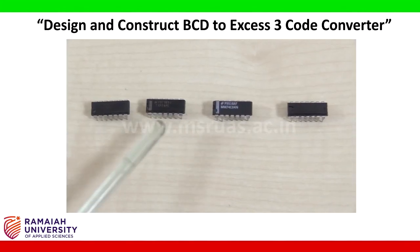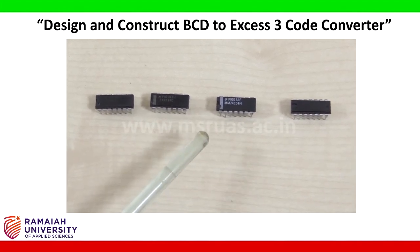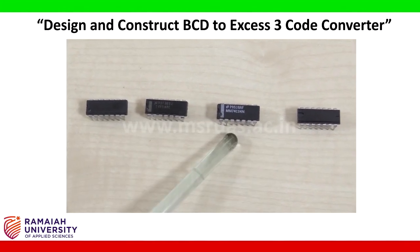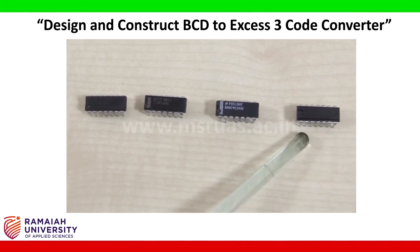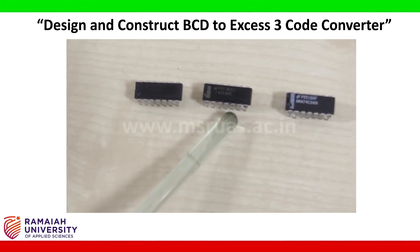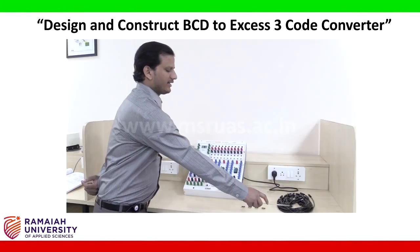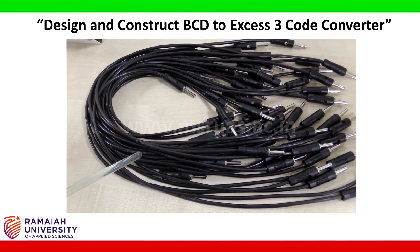ICs. So these are the 4 ICs which we are using to construct the given logic diagram. One is OR gate, the second one is AND gate, third one is NOT gate, and the fourth one is 3 input AND gate. The names of the ICs are 7432, 7408, 7404 and 7411, and patch cords. These are the patch cords we are using to connect the logic diagram.